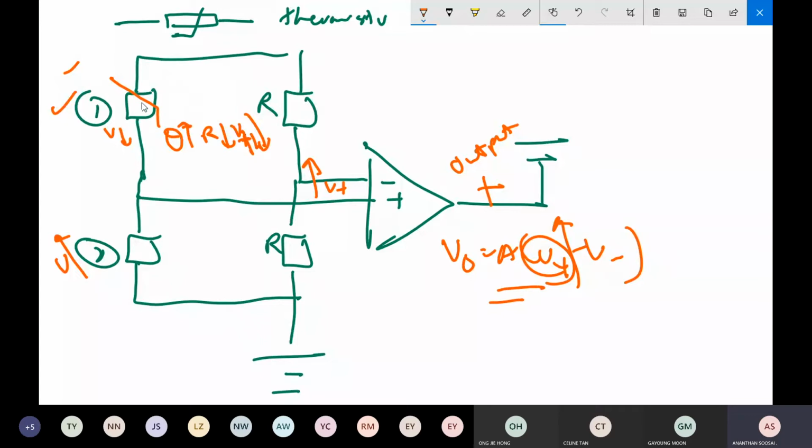Why you need to place it on top. Start with the temperature rise. Temperature rises, resistance of the thermistor drops, the voltage across the thermistor drops. Therefore, voltage input of positive rises. So V positive is most likely greater than V negative. Output is going to become positive, and you switch on the alarm. Each and every part carries marks, around 3 marks I think, for the explanation.